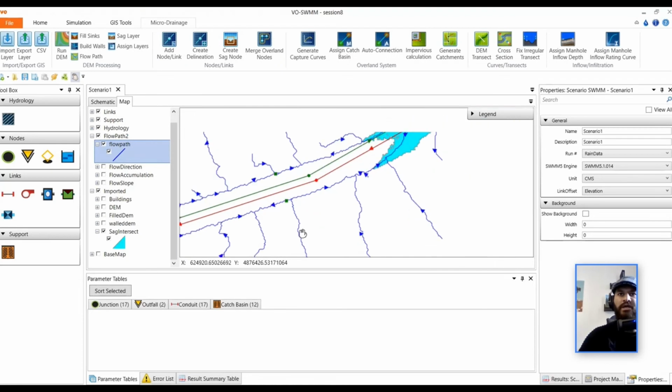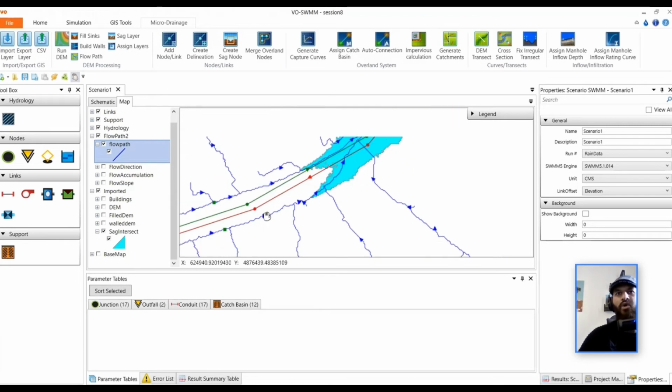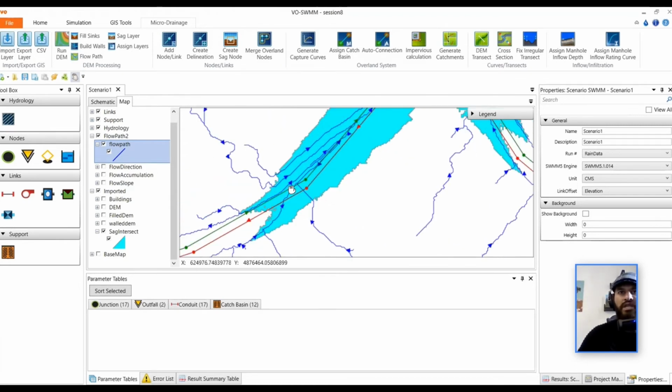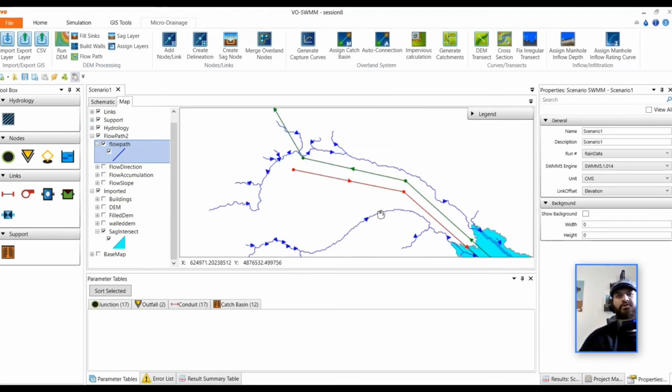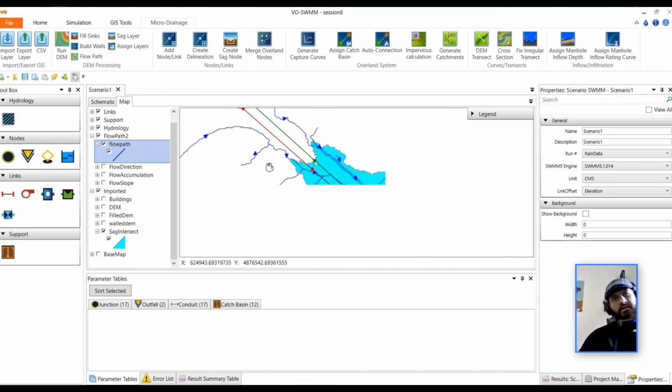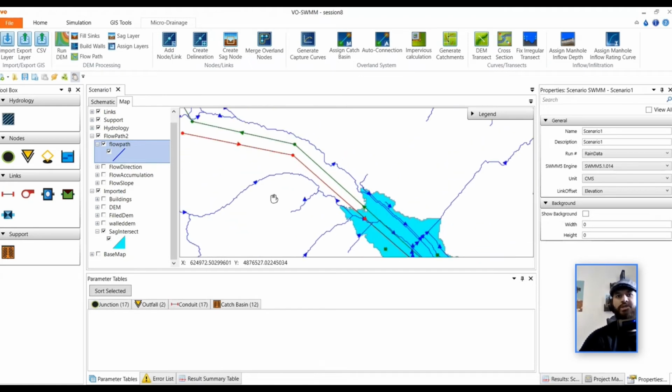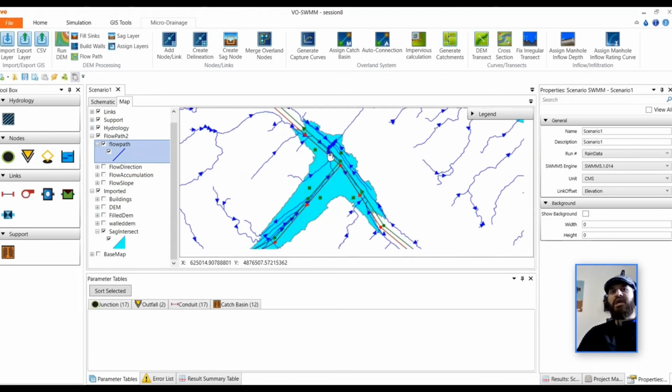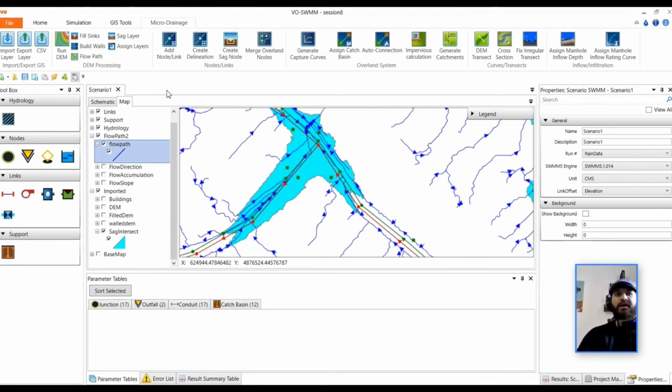And I'm going to place one here because we have two catch basins here. And same thing is going to be connected with this sanitary manhole. And probably one here too, because we have one sanitary manhole here. And in the other place, we have one sanitary manhole, two sanitary manholes, and potentially I will just put one here as well. So in order to place them, what I can do is I can just add these junctions